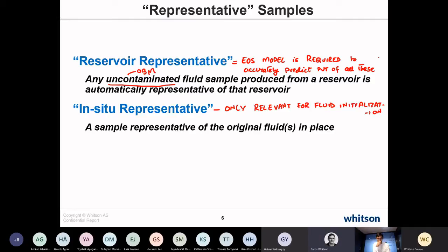And in most cases, relatively early in a field development you have production samples that are collected during production tests that have no oil-based mud contamination at all. And we take all of those samples, all of the PVT data from those samples that are quality checked and approved. We use all of those samples for developing the equation of state. And we don't use any of the samples that contain any level of contamination.